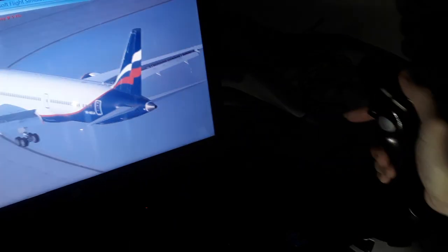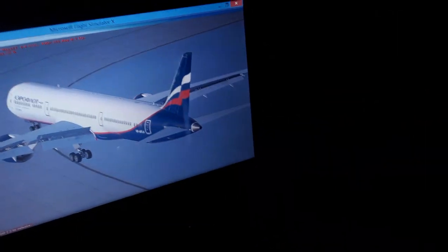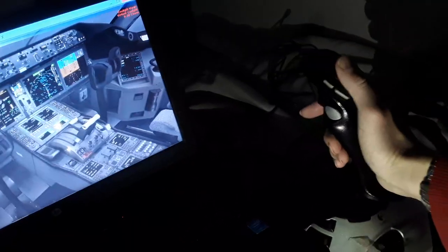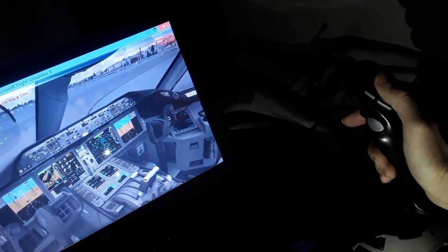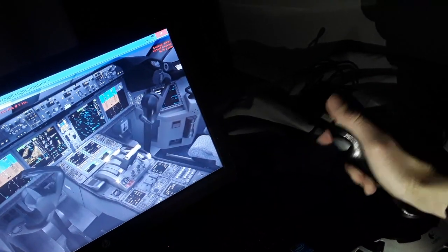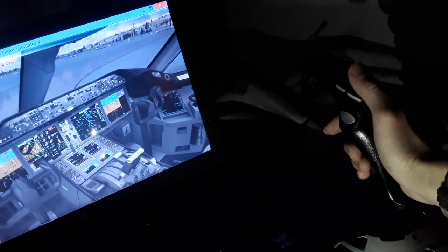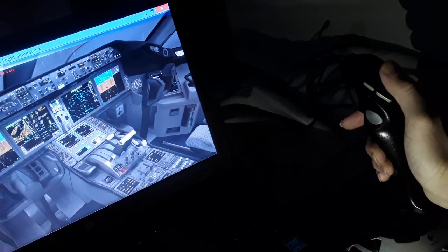It is the yoke back and forth in the Boeing for controlling the tail like this. So you see the yoke in the Boeing up and down. In the Boeing aircraft, both sides are interconnected and move together simultaneously, rudder pedals, control wheel. Not like in the Airbus where you have side stick priority, in the Boeing they move together. So you may climb and descend with the elevator like this.